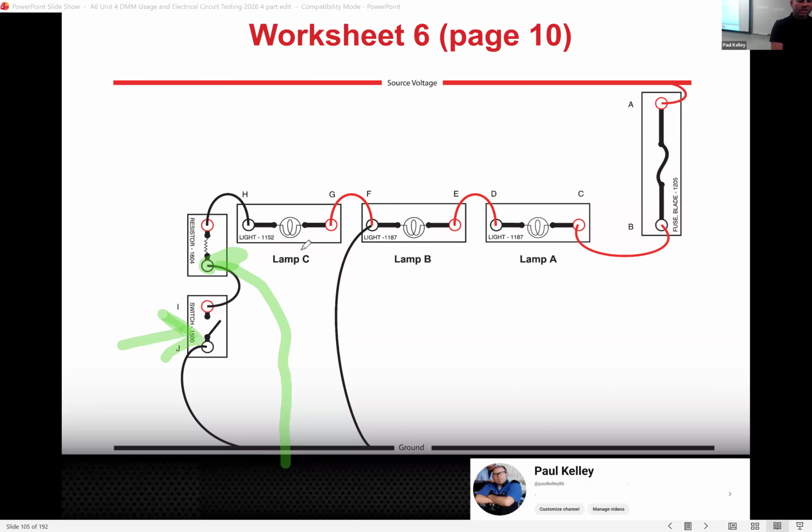The switch. So what's going to happen in this circuit if it's shorted to ground at that point? What happens when I open the switch? It doesn't make any difference. It's got 12 volts all the time, and it's shorted to ground, so that means whether I open or close the switch, it makes no difference. They're turned on all the time, right?